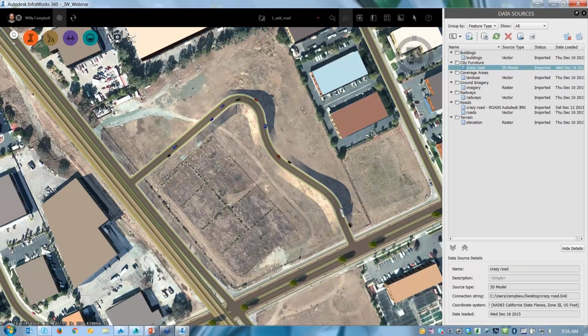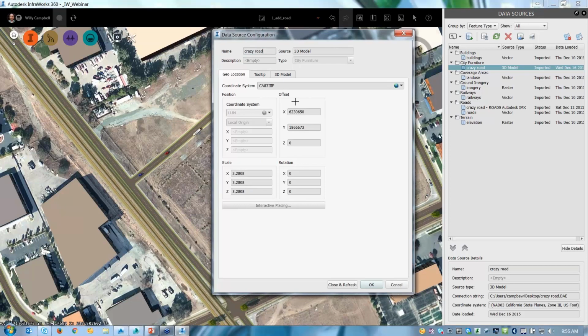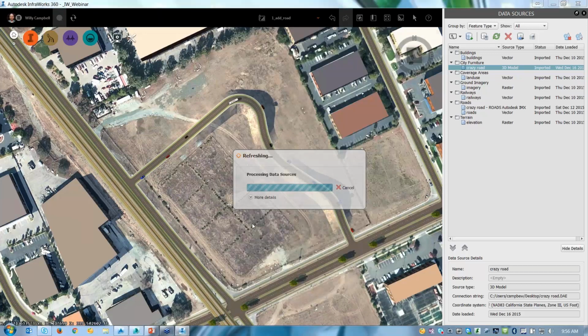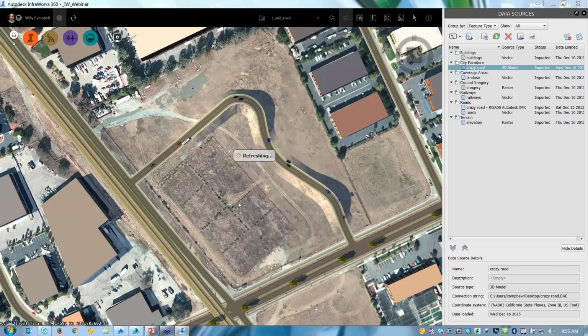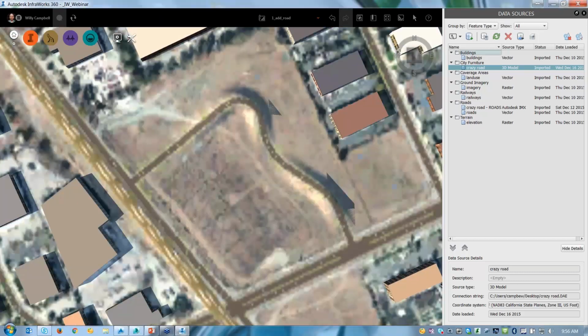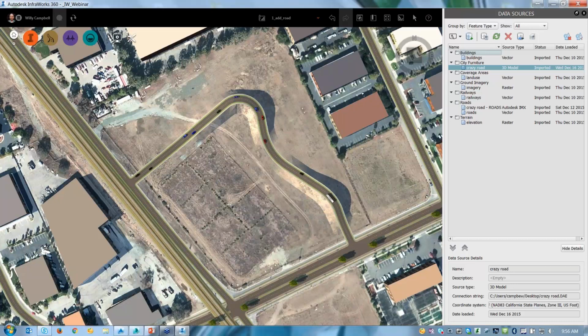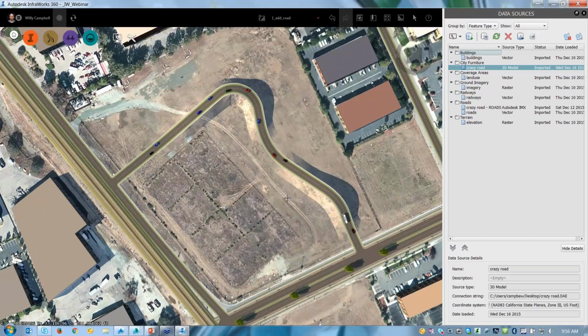So to be able to fix this, what I did was I come in here to the offset and I started changing these numbers by a factor of 5. So out of the 7 digits that are there, I changed it by a factor of 5, and I eventually came to realize going positive was the wrong direction, but changing this from 50 to 37, and in the Y direction from 70 to 73, and so I started out X and got it lined up, and then changed the Y by a couple and got those lined up. By changing those numbers slightly, you can see now that everything lines up like it should, horizontally and vertically in my road.